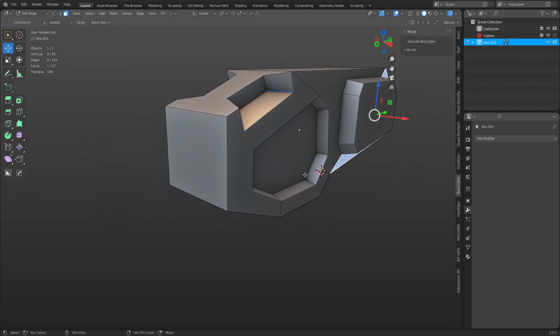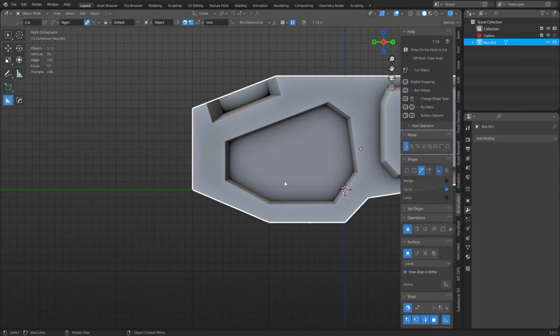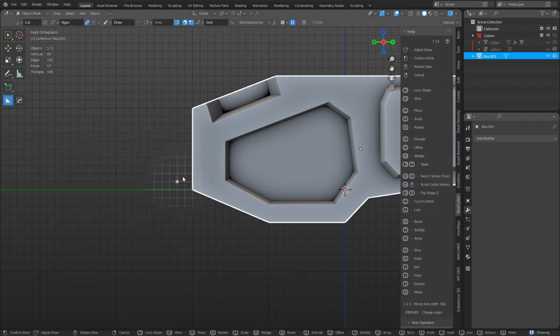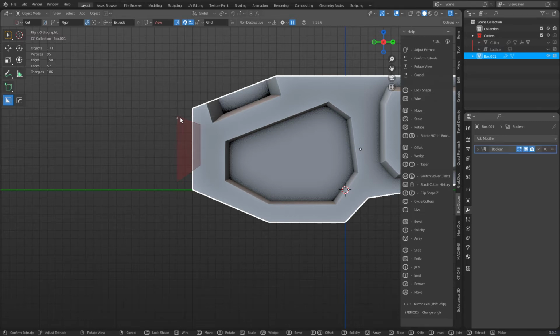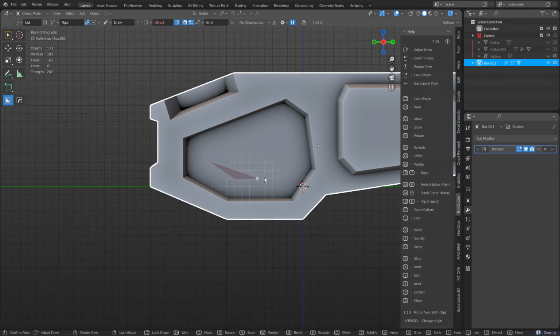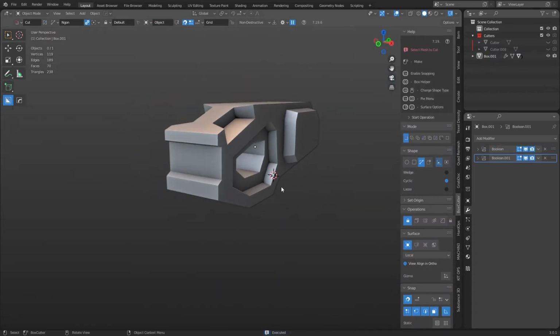All right, so let's make a little cut from the side here. When you have something in the side view, this is usually when I do laser cuts. And a laser cut is very simple. Instead of defining the thickness by hitting the E key, you just do a double click and it does a cut all the way through the object. So if I wanted to do another one here, I could do that just like that, right?